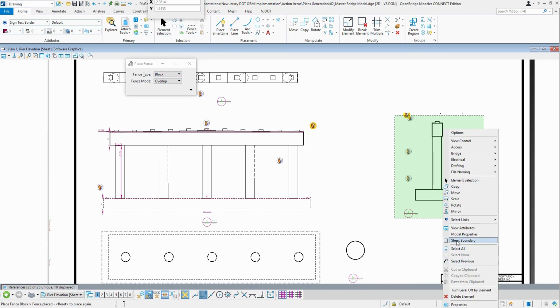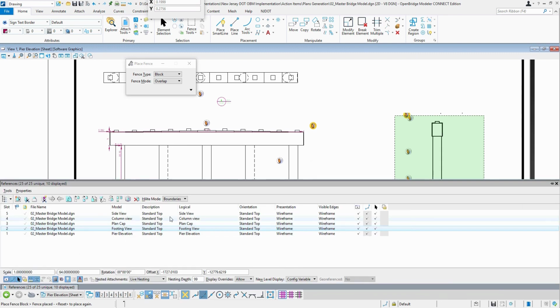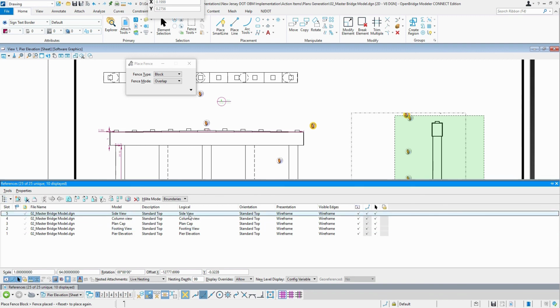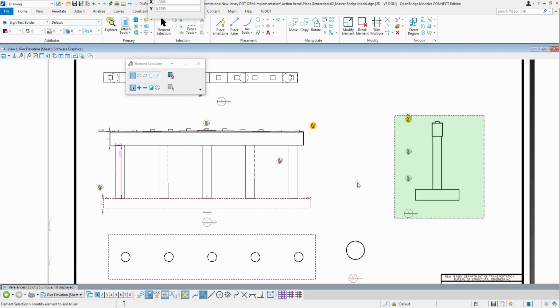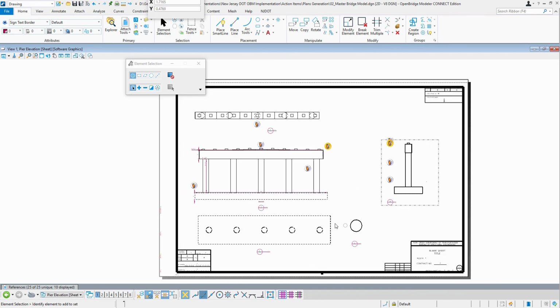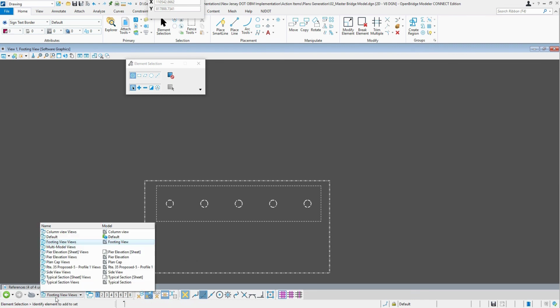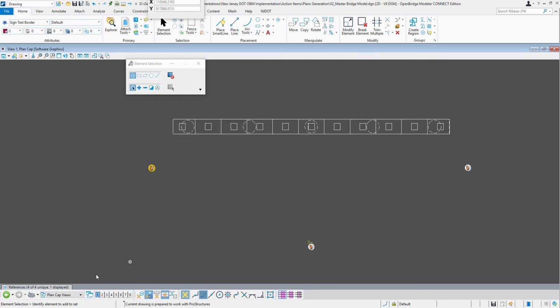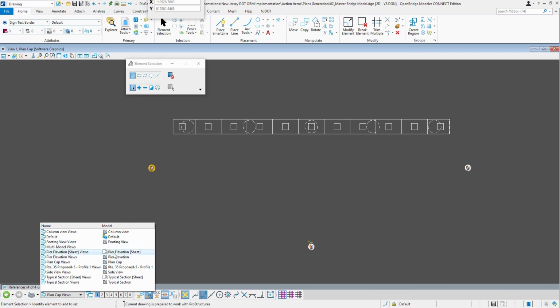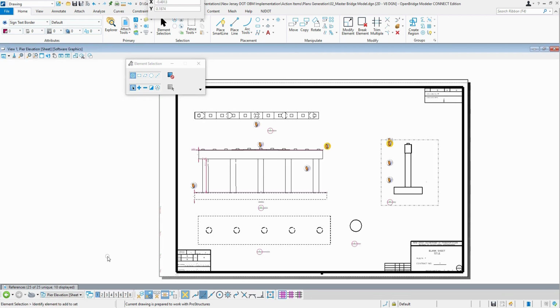Now this is just kind of a standard MicroStation operation to do that. One more time by reference. Apply a clip boundary into the column view and the top view and side view. That should be done. The markers, as you can see, these little bubbles, you can control with the view attributes, display markers off. But all the drawings are generated and all of these drawings are composed, and that's the process. That's what it's called, drawing composition, just to deliver that.